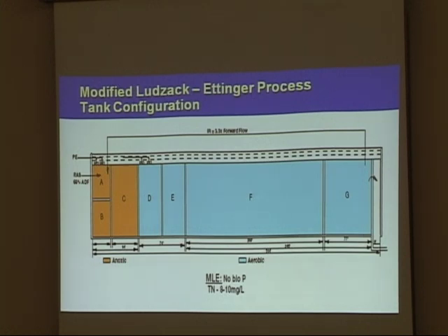As we mentioned earlier, you wouldn't want to internally recycle too much. If you're going too quickly, you get a lot of high DO. You could be introducing DO into an anoxic selector. But you also want to make sure you're internally recycling enough so that you're getting the highly nitrified mixed liquor into that zone and optimizing the nitrate removal as much as possible to drive the denitrification and the release of the nitrogen gas up to the atmosphere. So there's a little bit of a balancing act there to find out what the optimal setting is going to end up being for the speed.